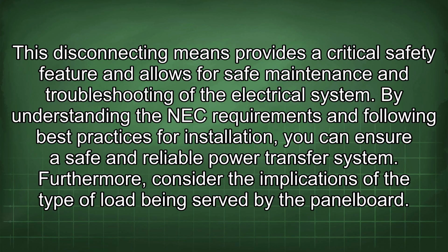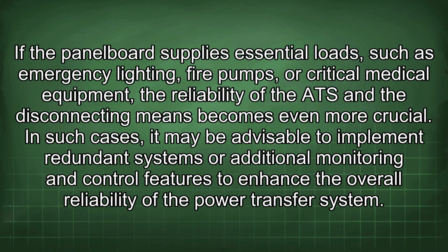Furthermore, consider the implications of the type of load being served by the panel board. If the panel board supplies essential loads such as emergency lighting, fire pumps, or critical medical equipment, the reliability of the ATS and the disconnecting means becomes even more crucial. In such cases, it may be advisable to implement redundant systems or additional monitoring and control features to enhance the overall reliability of the power transfer system.